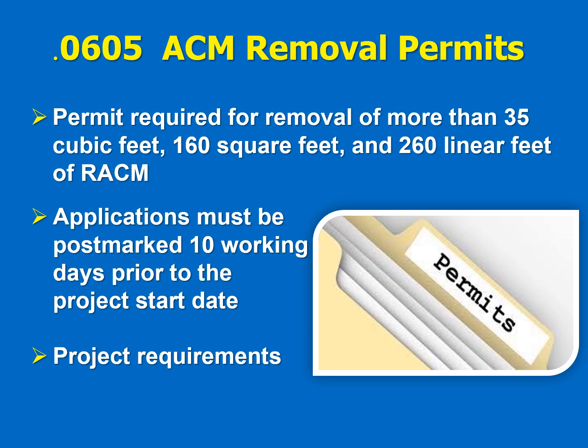So, .0605, the ACM removal permits. A permit will be required for the removal of more than 35 cubic feet, 160 square feet, and 260 linear feet.